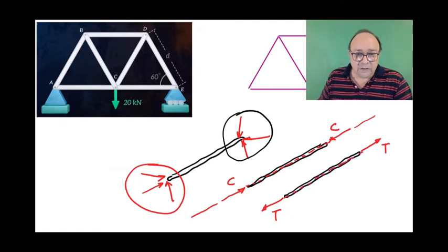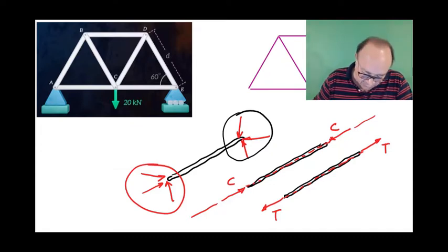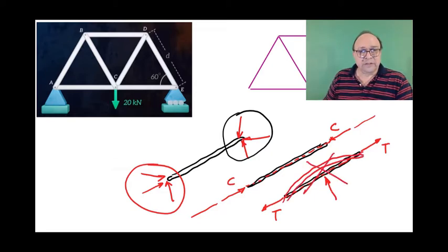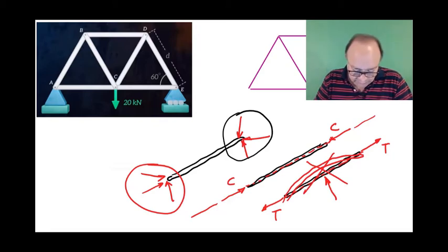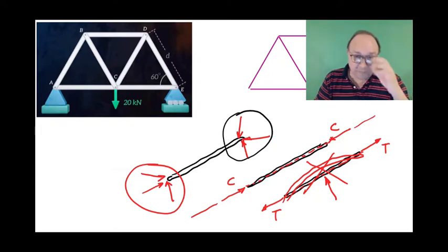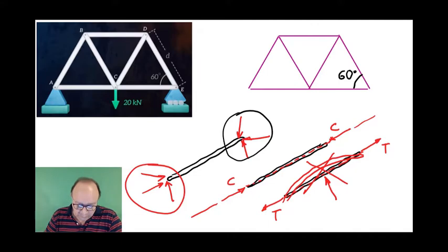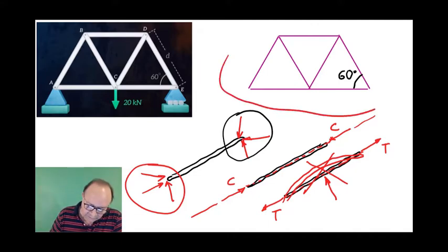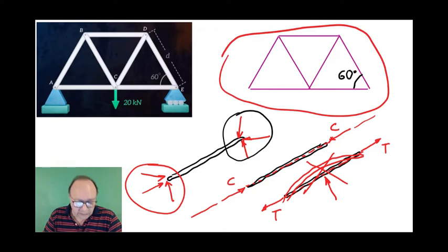Very important concept to make sure to understand: that's what makes a structure a truss, that all the elements are subject only to compression or tension. That's it. There is no flexion. If you put a load over here in the middle, that will cause bending like this. So that is not a truss element. He mentioned that very quickly, but I want to point it out very carefully here. It's a very important concept. And now, he mentioned that in order to solve these problems, you make a free body diagram. So this will be like the free body diagram of the truss that he analyzes there.